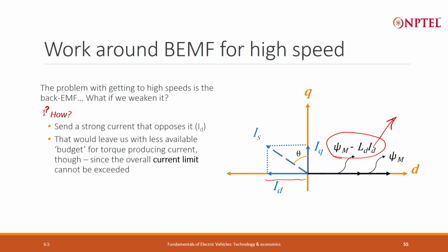We will look at it in little more detail, but what I want you to appreciate before that is that there is also a current limit operating. I am not trying to operate close to the current limit, because when I am going very fast, I am not trying to overcome some load or go uphill or things like that. So, I do not require the full current. I have a lot of surplus current left with me. I can afford to spend it on the ID, but the more I spend on the ID, the less current I will be left with to spend on IQ, which is what is mainly creating the torque. So, it is a tricky situation. I am reducing the available IQ by spending more on ID, so that I remain within the current limit, but I think that will help me get more torque.